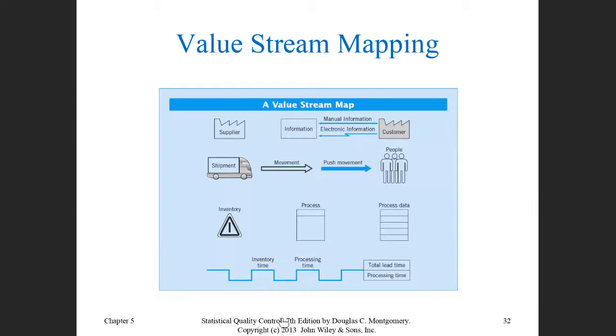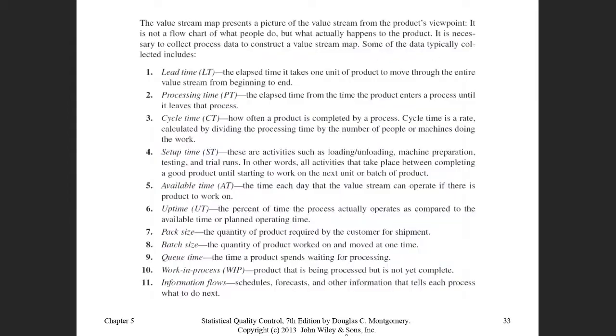But the difference between the circle shape and the value stream mapping is that the time is calculated in the value stream mapping: the processing time, inventory time, and lead time. The cycle doesn't do that. Those times need to be calculated, and it also helps you convert the map to a simulation in Arena, so you can simulate the process.